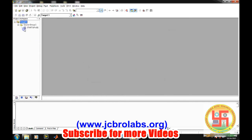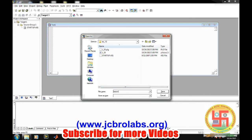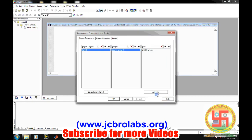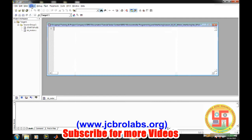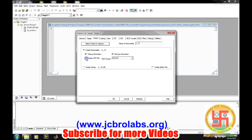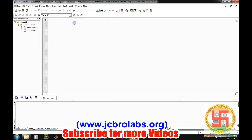Yes. So we will write the code in C language. So let's save it, like DC motor.c. Okay, now it's saved. Now let's add it to the project, DC motor, add, close. Okay, now in the options for target, take 12 megahertz, and in output, create hex file, and then okay. So our project has been created.